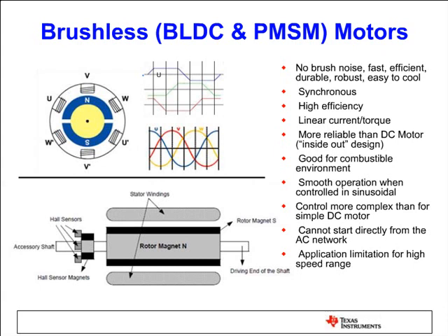But on the other hand, in the PMSM type of motors, the stator has more slots, like 50 slots, 60 slots, 40 slots, depending on the structure. And the windings are very carefully distributed to create a sinusoidal waveform in the air gap. So again, if you look at the motor terminals using a probe and spin the rotor using your hand, you will see sinusoidal back EMF waveforms. So the difference between PMSM and BLDC type of motors is nothing but the stator structure. The rotor is pretty much the same.